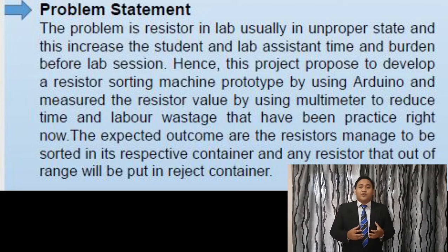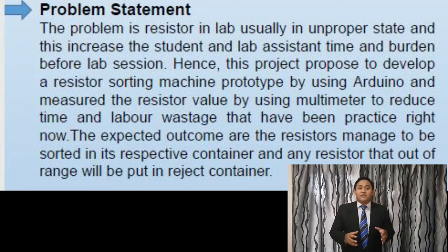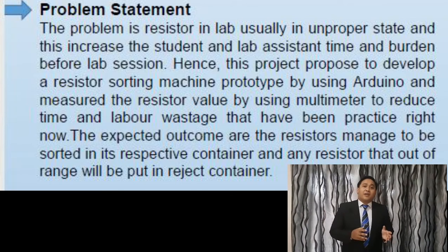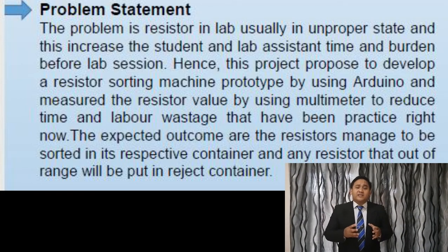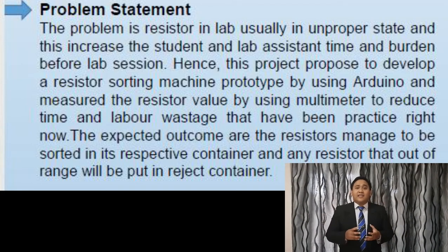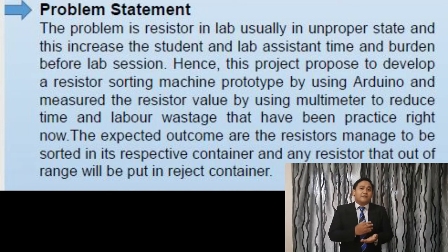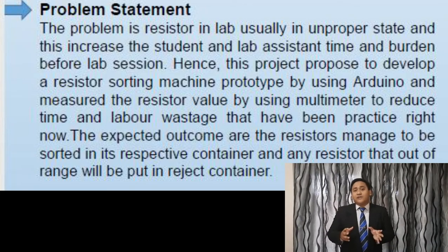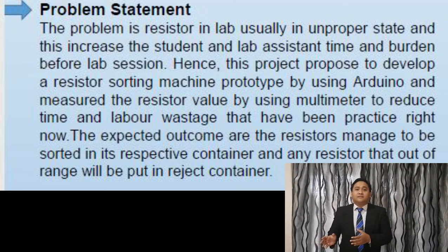Hence, this project proposes to develop a resistor sorting machine prototype by using Arduino to measure resistors by using a multimeter, to reduce the time and labor wastage. This system is expected to measure the resistor and make sure the resistor falls in the correct bin, and the out of range resistor in the reject container.